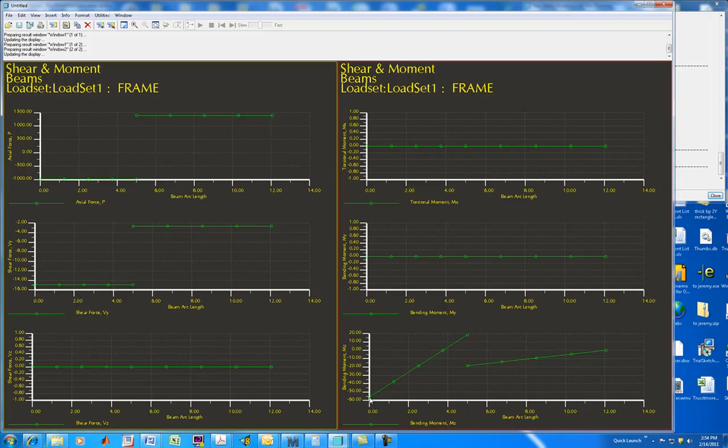We have a moment at the wall where this thing is cantilevered. That reduces and reduces and actually changes signs and goes to a positive 20. Notice where it connects to the other beam. The only reason there's a discontinuity is that there's a change in the sign of the moment because the beam sort of flipped over. But it's the same magnitude moment, so that's the moment that's being transmitted through that beam, continuing up to the connection point at the wall with a moment of 0 because that had a ball joint on it. So that one makes sense as well.